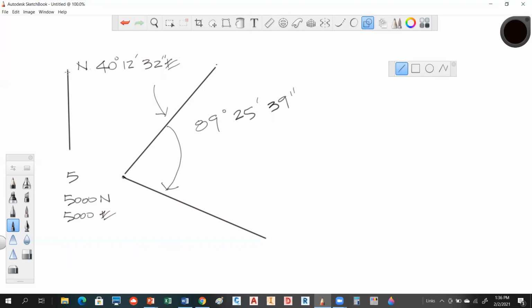So we're going to say this is north, like this. Okay. So you also shot a distance here, let's say of 560.26 feet. So we got this point out here. We're just calling it 100. We need to know what is the northing and the easting of this point. We don't know that. So this is not an inverse. This is what we call a direct routine. So who can tell me what we need to do first?